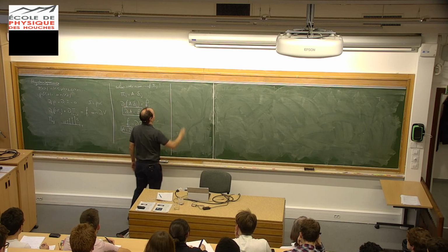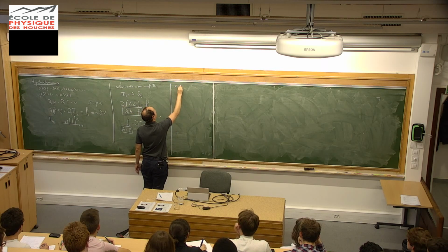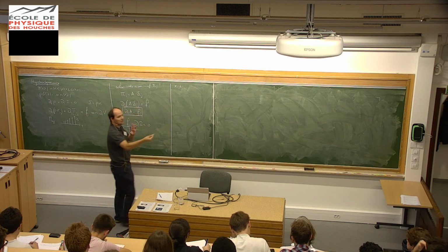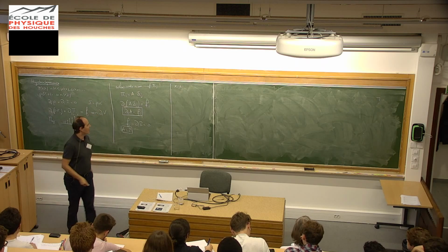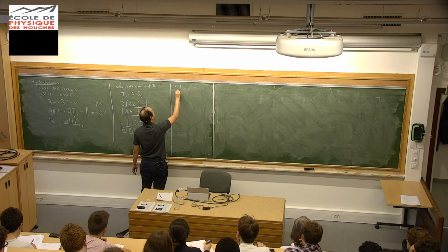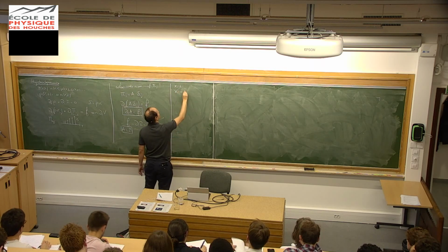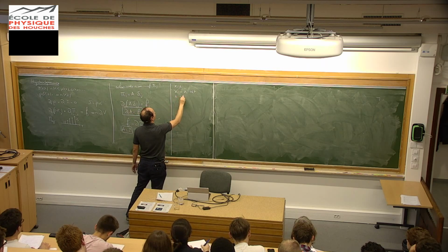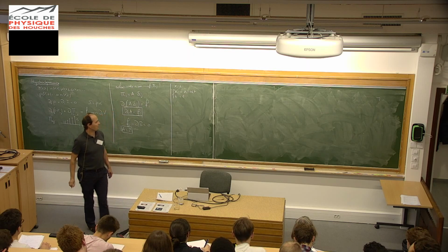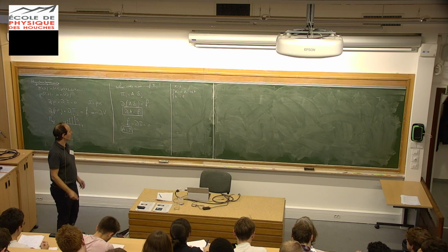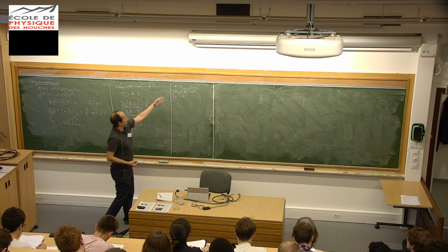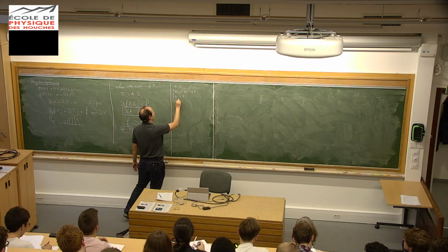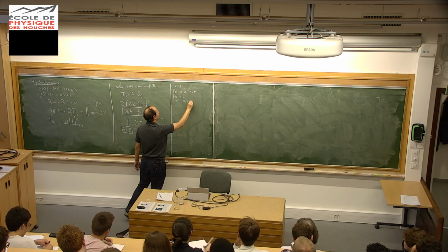And so here I work in a frame where positions are defined by x_i and time t. And so I'm going to work in a new frame which moves at a velocity u with respect to the lab frame. And so I define a new position x'_i, which is equal to x_i minus u_i t. And the t' will obviously be the same, because I'm not considering Einstein relativity here. It's just standard Galilean relativity. And obviously, in the new frame, the velocity field will be modified, because the velocity in the new frame will be simply v'_i is equal to v_i minus u_i.